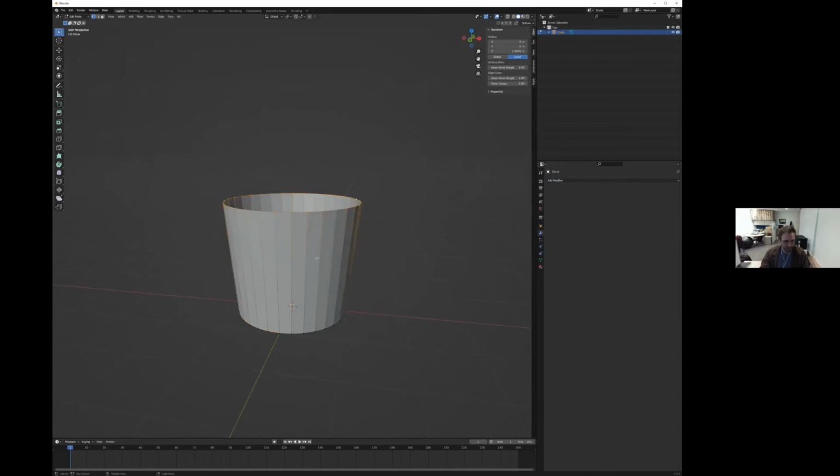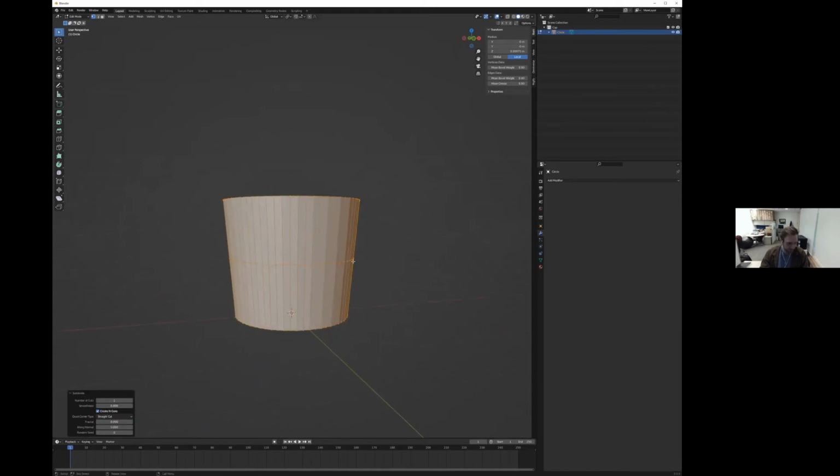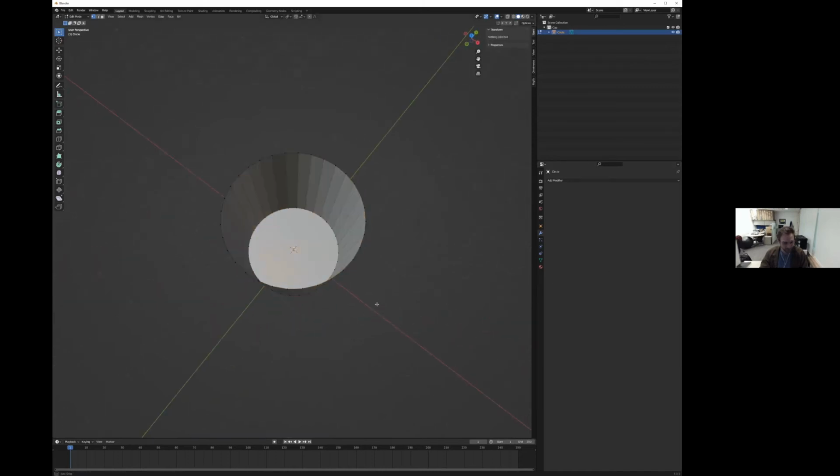And so if I am looking at this and I click all of it and I press right click, I have this option, subdivide. So if I click that, I now have subdivided each face. Now, this isn't what I want to do. You guys don't need to follow along here, but just know that that's kind of what the operation is doing, but non-destructively. Okay, so I can't do much. I have to go back. Whereas if I just added a subdivision modifier, I can then toggle that on and off, which we'll do in a second.